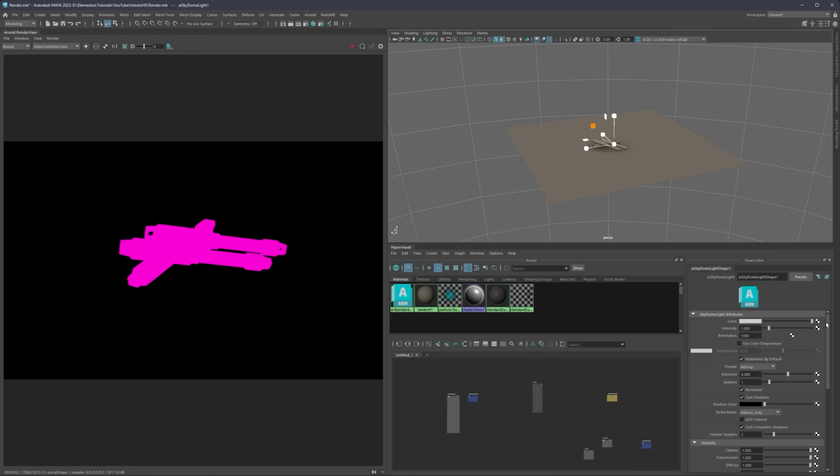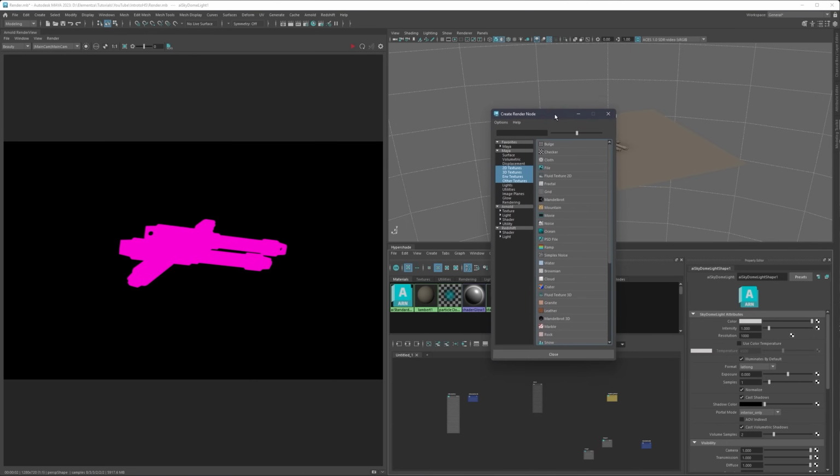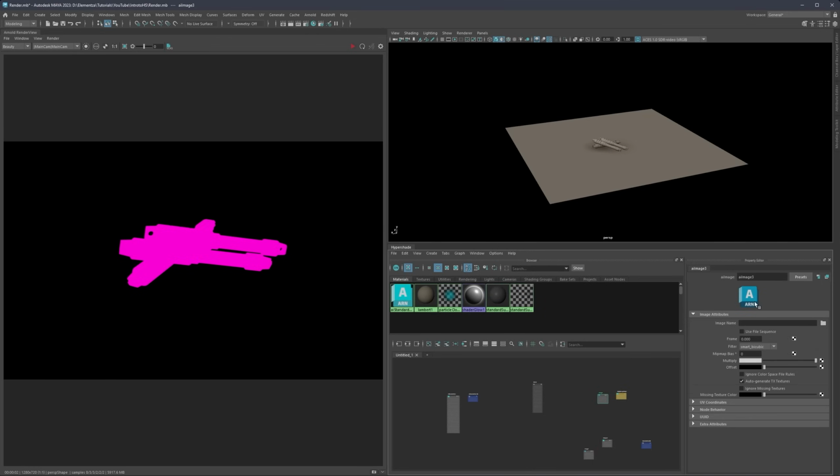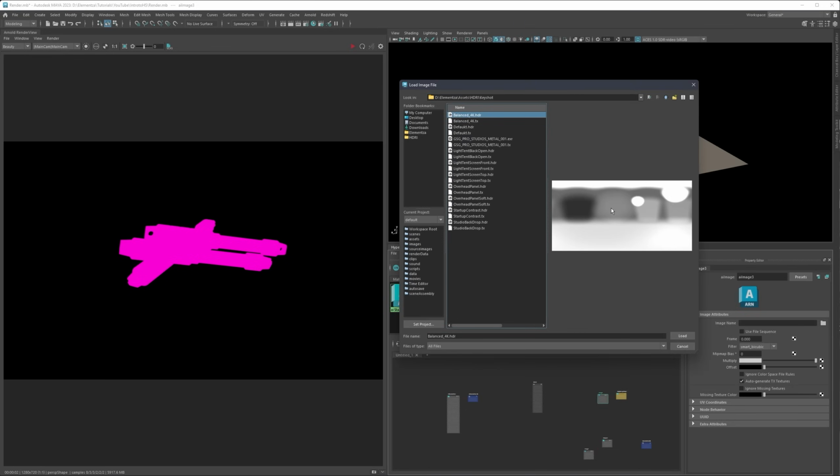And let's go here under color, and here under this checkerboard, we're going to click on it. That simply means that now instead of the slider and instead of a color, we are loading in the texture. And again, we need to go under Arnold and use AI image. So simply click on that, and now we simply need to find an HDRI somewhere. You can use anyone you wish, but here what I would recommend is definitely an HDRI with very, very neutral contrast. That means that it's very bright and not so much, let's say, hard contrast between light and shadows. So that kind of has a neutral form. I can show you. So I have something like this, which is again very, very neutral, not too contrasty.